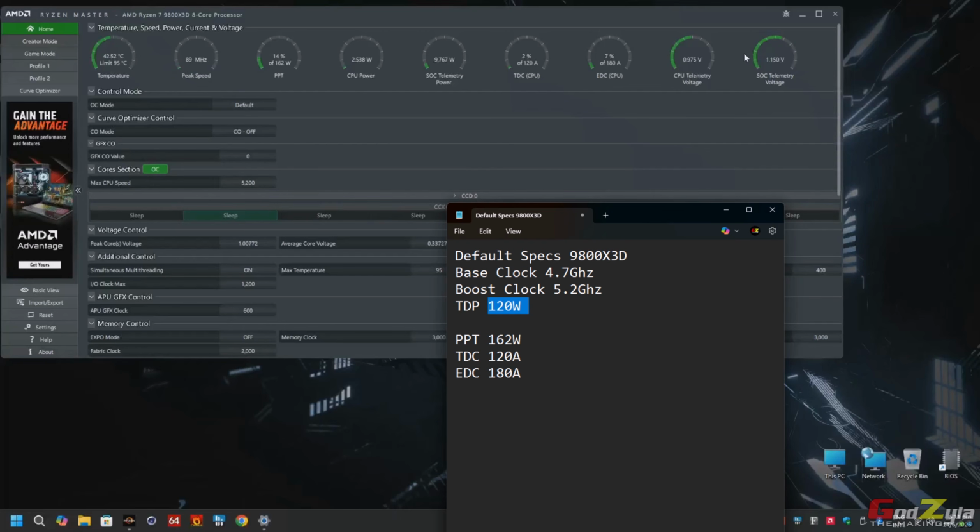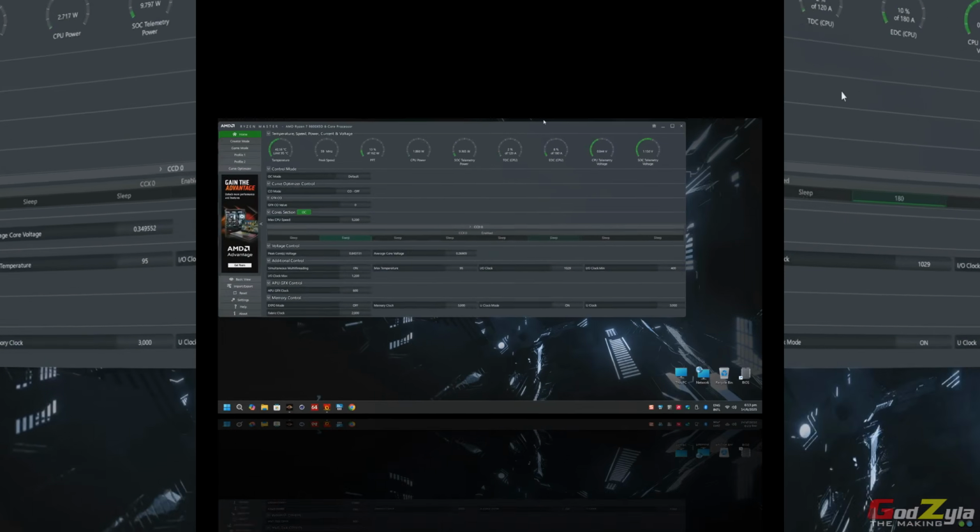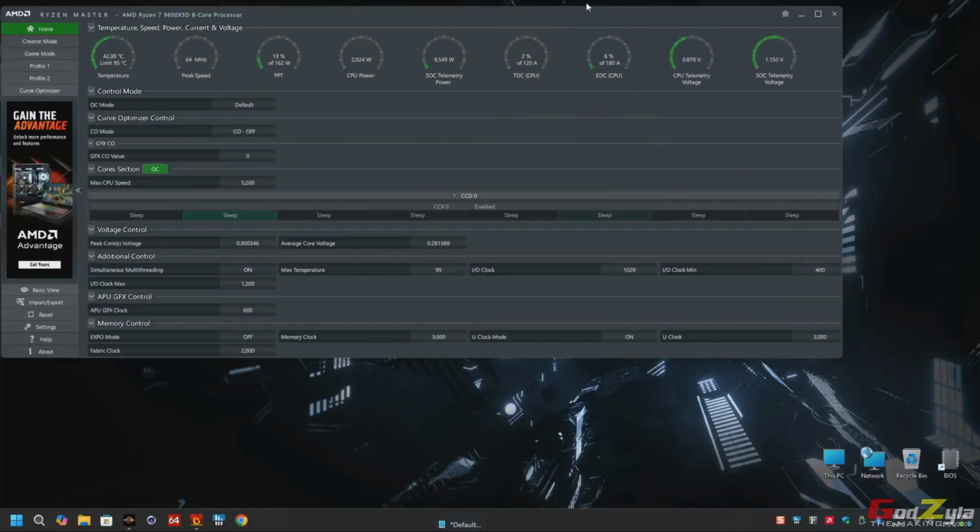Also, as mentioned to you, later on I'll show you the SoC voltage, whereby I told you not to run above 1.2. It's best to stay below 1.2, which I'll show you with another set of RAM. That will happen if you do not configure it properly. After you have done all the markdown and I've explained what's going on, take note of the CPU power and the SoC, which is not a bother here because I've set it to 1.15. Just take note of the CPU power.